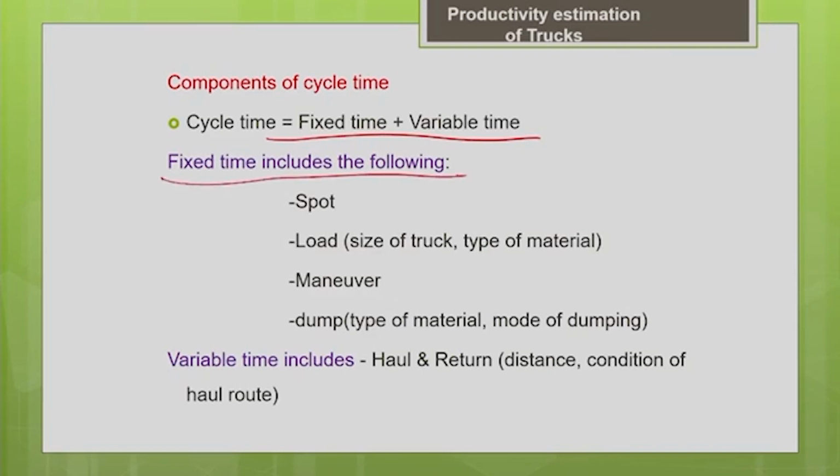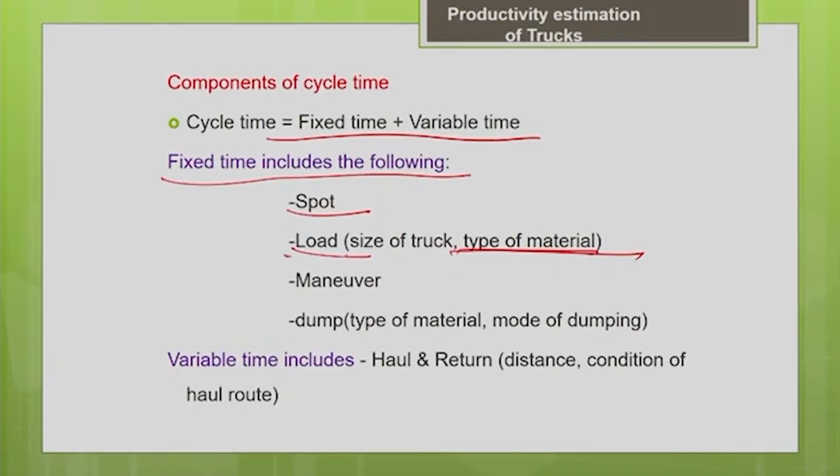So what comes under the fixed time? Under fixed time, you have spotting of your loader and loading the truck. Obviously it depends upon the size of the truck and also upon the material. Some materials are easy to load. Dry earth, sand and gravel are easy to load. But blasted rocks and clayey material are difficult to load. So all these things will affect the loading time. Then whatever maneuvering, changing gears and turning.